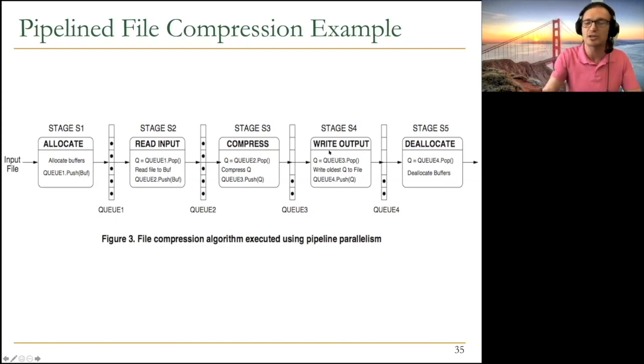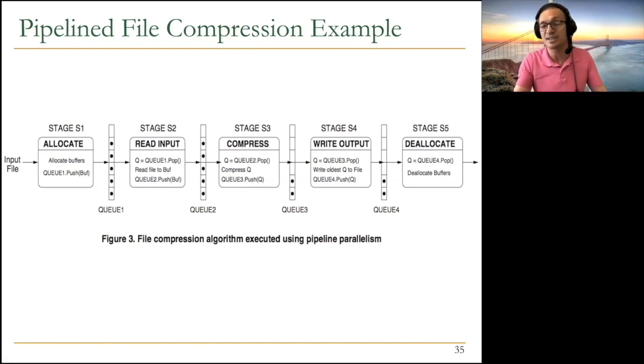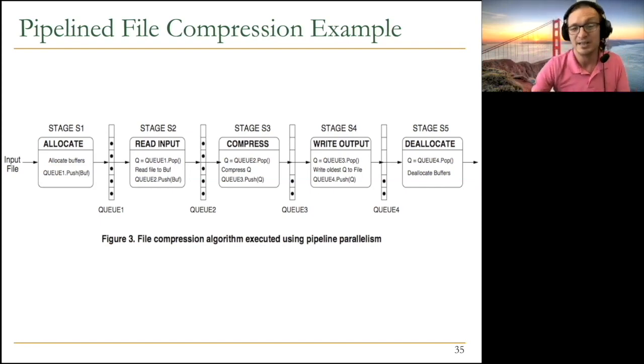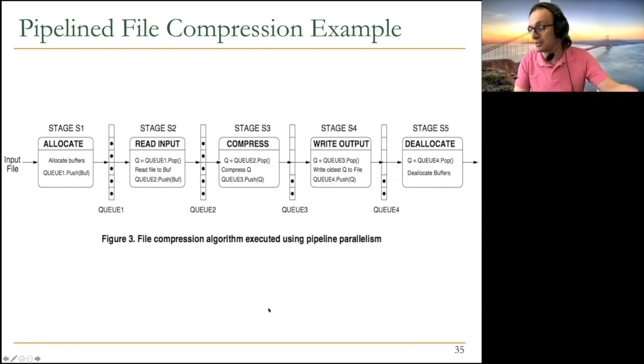If you do this in software, of course, you go through memory. But if you do this in hardware in an accelerated fashion, the way we are talking about systolic arrays, you don't need to go through memory each time you do this. Basically, with each input element, you don't need to go through memory in any of these stages until you output it. Okay, so this is one example that you may want to think about.